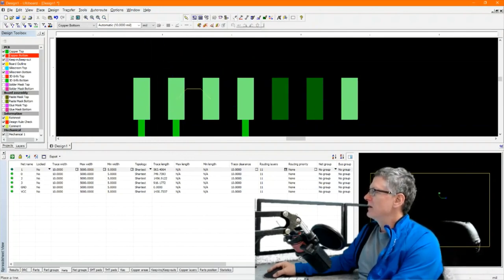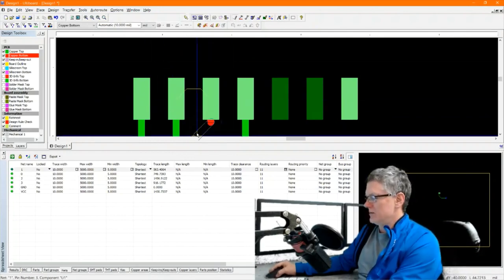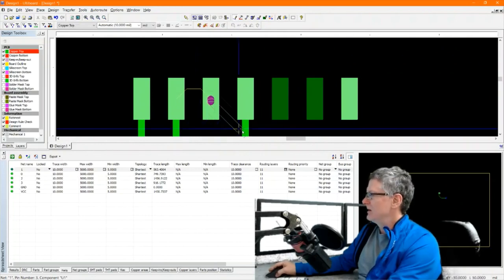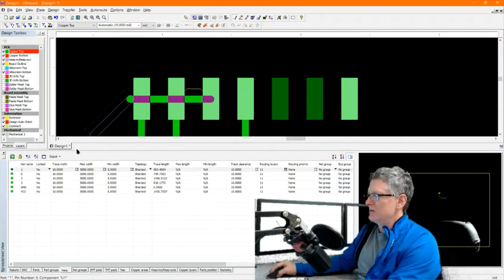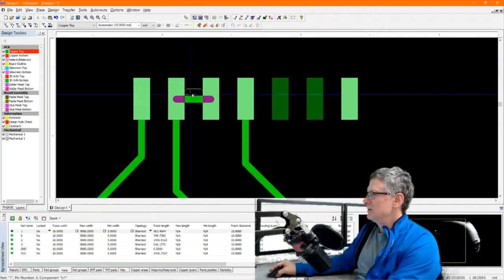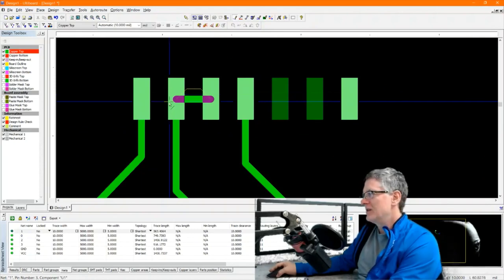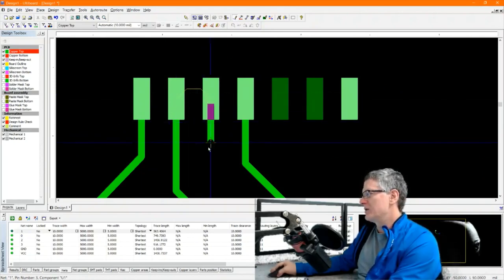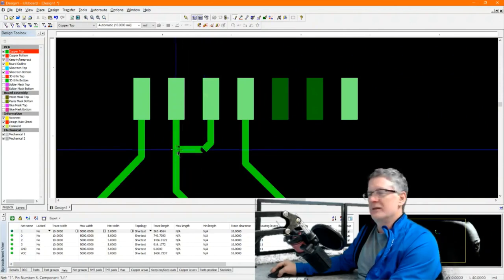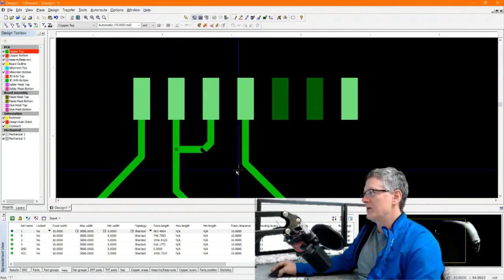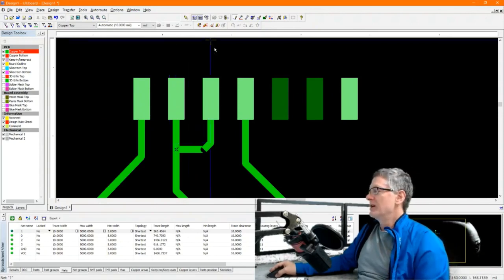These 2 pins. So what I'm going to do is, oh, wrong side, F2, flip sides. I am going to move that down. I could run a quick trace across here, but I've found that after the part gets soldered on the board, it's kind of hard to tell if that's a trace or some kind of piece of crap caught between the pins. So usually what I like to do with something like that is bring it out outside of the chip so it's visible, and I make the connection outside rather than underneath.